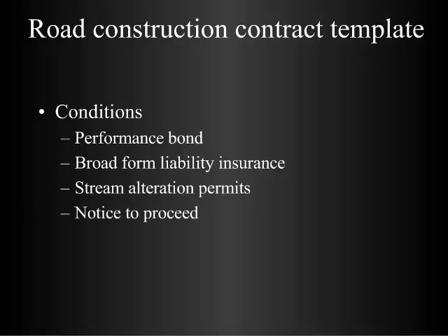The other thing to put in the contract is that you'll have a starting date and an ending date, but you want to make sure that they don't actually start the project until you give them a go-ahead. They can move their equipment on. You want to make sure you have a pre-work meeting or a walk-through on the ground with the supervisor or whoever. It may not be the same person you've signed the contract with. He may have a lead person on site. You want to have a meeting with them ahead of time before they start to make sure that everybody understands what the expectations are.